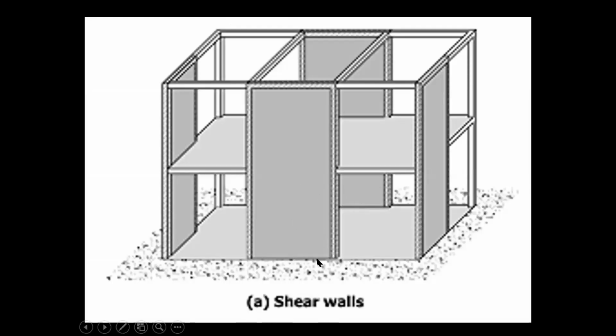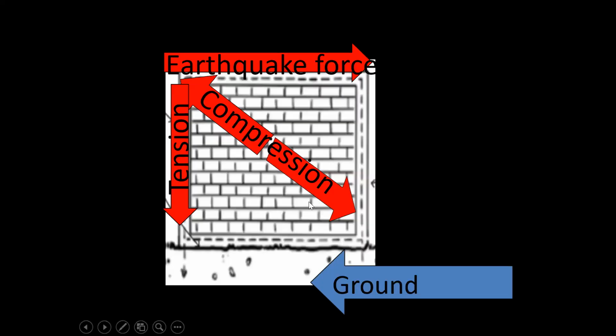Now, as you know, shear walls are appropriate in a wide span building. If it's a wide span building, it means that maybe the shear walls are quite heavily stressed, and maybe reinforced concrete is the best material. But shear walls can be of different materials.